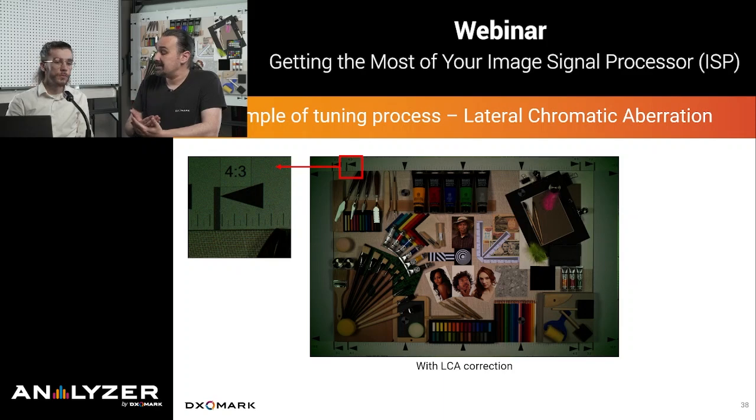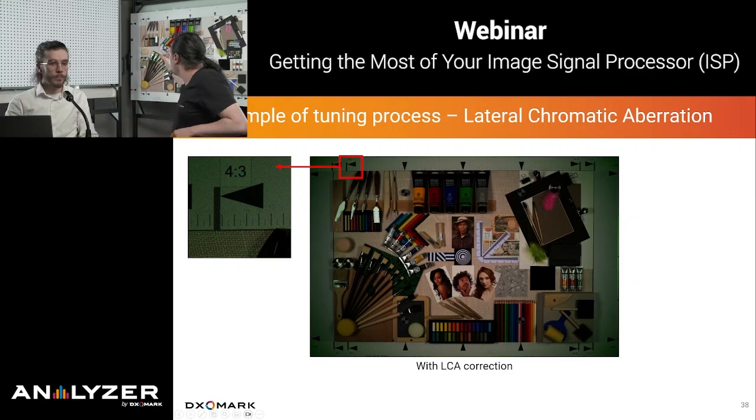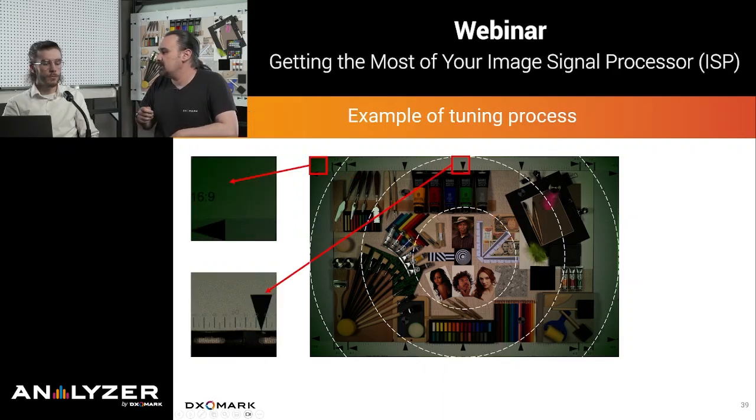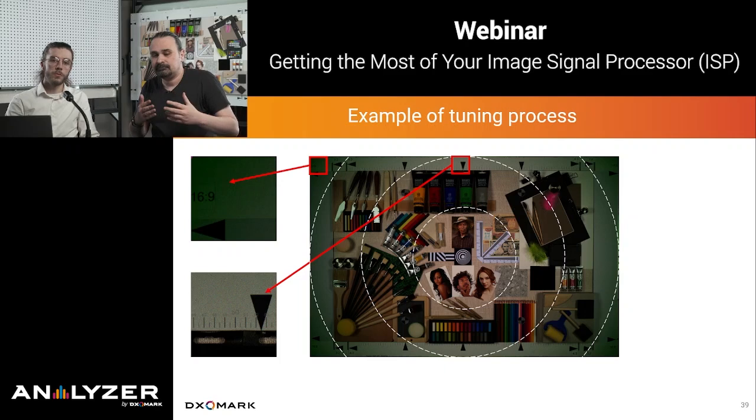that your lighting is uniform, because you have to be sure that in the scene this wasn't the case. Okay, my target chart is of a uniform gray all around, and when I set it up for testing, I also measure the center and the corner with the light meter to be sure that they're at the same level. So why is it darker in the corner than it is in the center? Well, this is a problem that has a lot of names, actually. We can call it vignetting or luminance shading, sometimes roll-off, fall-off, but they basically all mean the same thing. Because of the geometry of the lens, some elements are projecting a shadow over others, and you get less light in the corner than you get in the center.